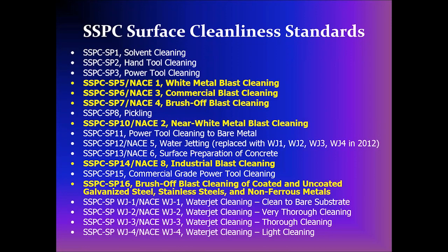Here's a whole list of SSPC surface cleanliness standards. The ones in yellow are the ones I'll be talking about. They're the abrasive blast cleaning ones. Notice at the bottom you've got the water jetting standards. That used to be SSPC SP12. They've now been broken out into individual standards for various grades of cleaning. They will be the subject of a future Lunch and Learn. But for now, we're going to cover the ones that are in yellow.